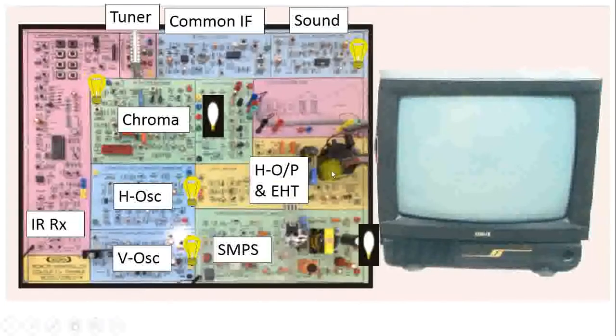That's why the boosted voltage, and this boosted voltage output is given by V output is equal to L into di by dt, where di by dt is nothing but rate of change of current through these secondary turns, and L is the value of this secondary turns, and hence V output L into di by dt is huge. That's why this extra high tension of 33,000 volt is generated with this EHT, and it is applied to the final accelerating anode, which is the requirement of this CRT based picture tube. Okay, so now